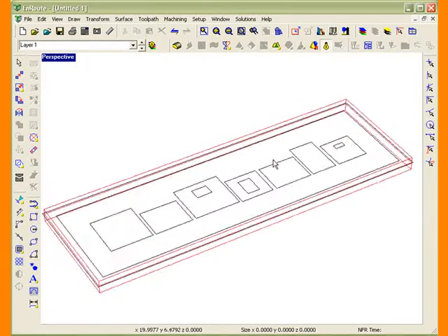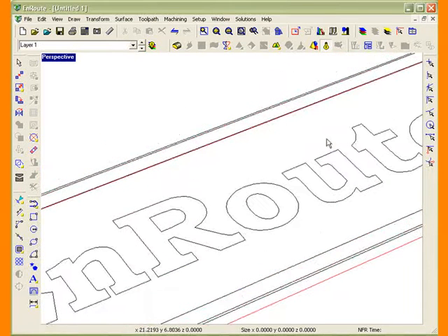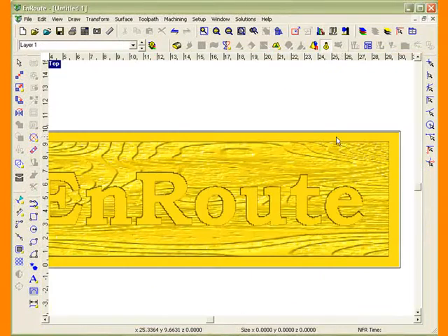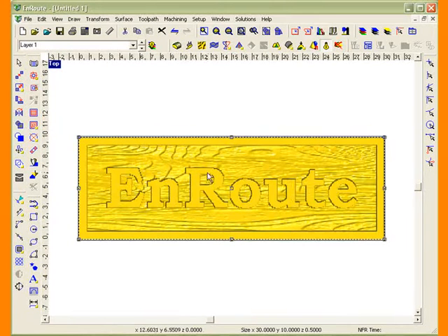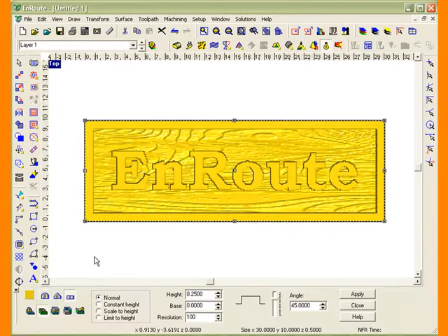So the next question would be, do we want to do anything with the text? I mean, we could just have this vertical text here, or we can actually come in here and select this. Now, since I have this text and it's right where these other shapes are, I can use these 2D contours to do something here, and I come here to create relief. Now my base should be 0.25, or let's see, we'll do a base of 0.35. That leaves 0.15 for some type of work here. Let's do a little rounded 0.15, and I'll do constant height.